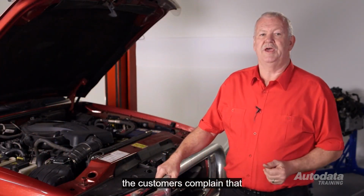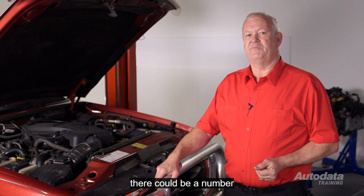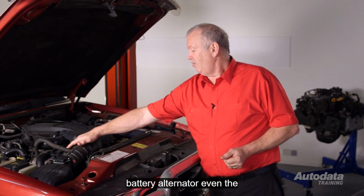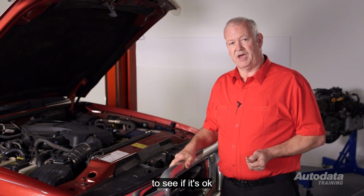The customers complain that after driving the vehicle at night, it's a little bit hard to start in the morning. Of course, there could be a number of faults that cause this. Battery, alternator, even the wiring. I'm going to do a voltage drop test on the wiring to see if it's okay.